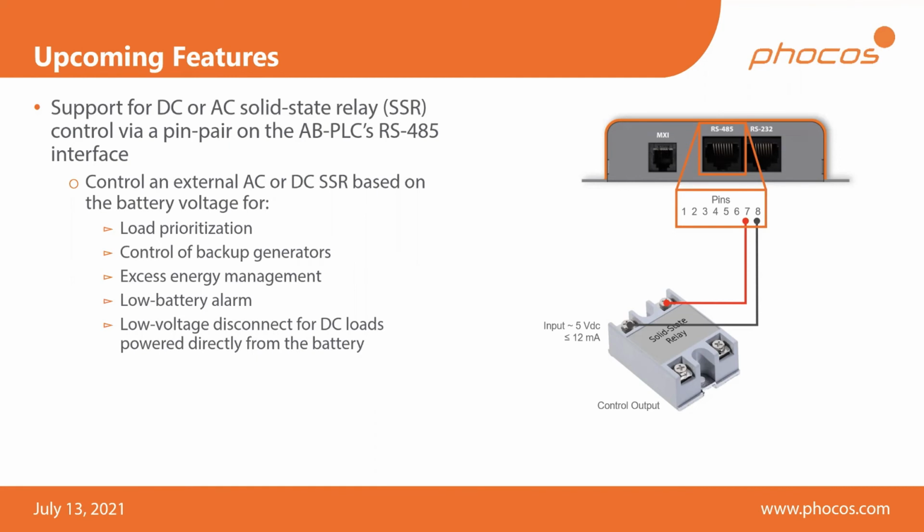The second last point is a low battery alarm. If you're really living off-grid, maybe you're in a cottage or something like that, it can be very important to know when your battery is starting to run low. And of course, you can use this as a switch, because as I mentioned, you can define at what battery voltages will trigger, and just give you maybe an acoustic or maybe just a lamp or something to make it clear to you, oh, my battery's running low, I better reduce my consumption to make sure that I maybe get through the night and the system doesn't turn off halfway through the night.